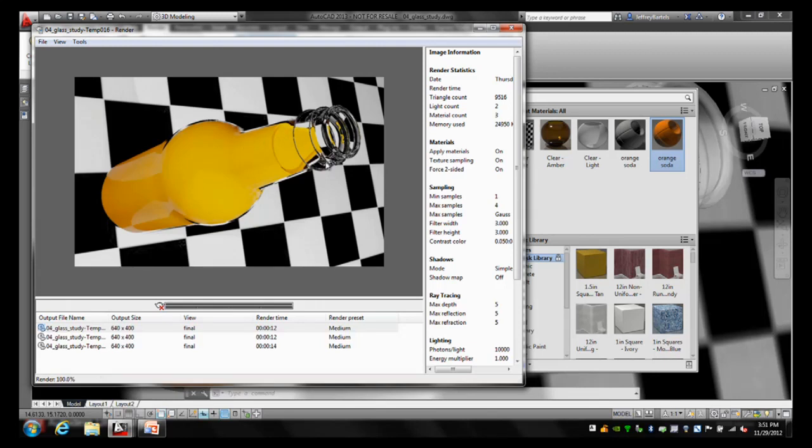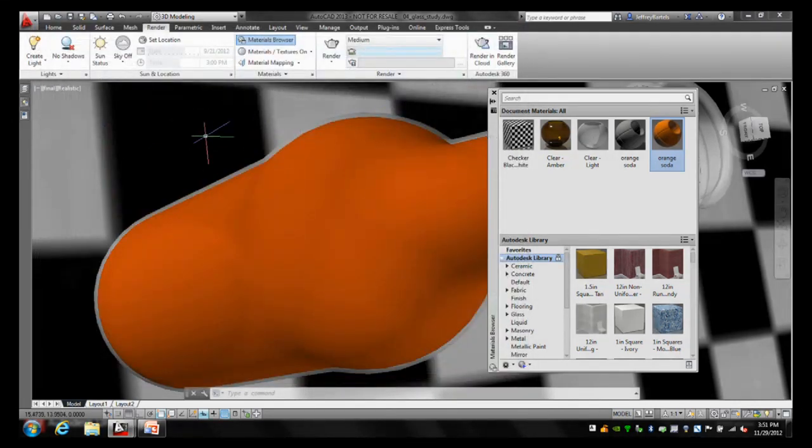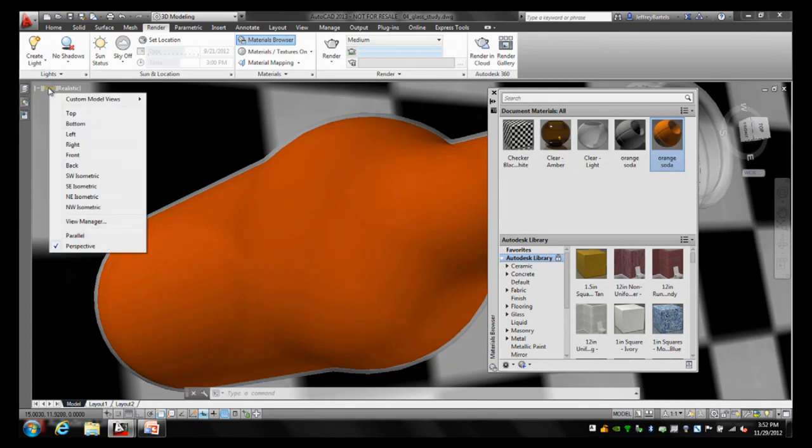Likewise, it's very dark up here at the top, and that's because the glass is reflective. It's reflecting the atmosphere of model space, which is black. So what I'm going to do is apply an image to the model space background such that the glass has something to reflect. Okay, let's try that quickly. To apply an image to model space, I'll go right back to my in-canvas menu. We'll come down to View Manager, same place where we saved a view.